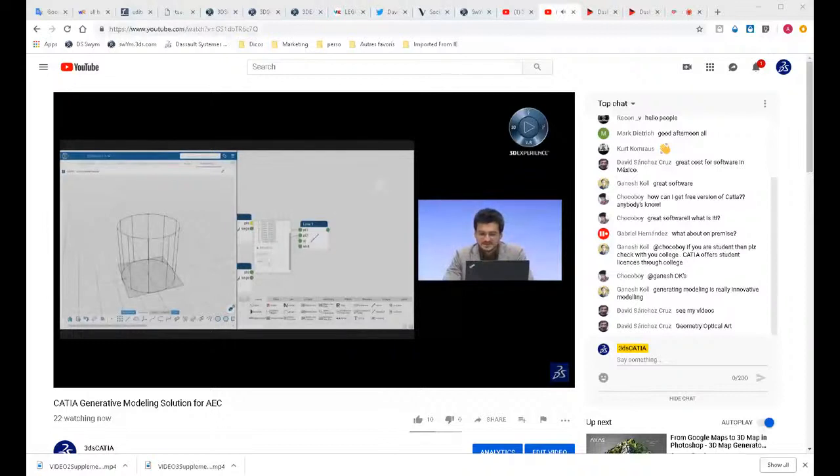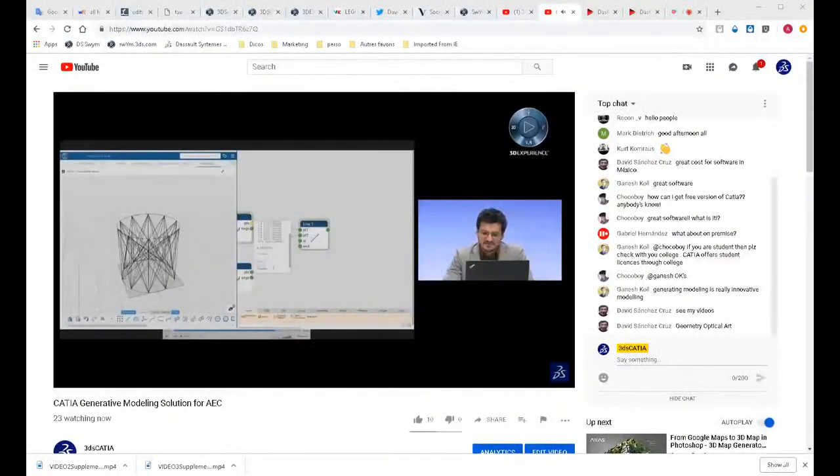Here I can actually embed a sub-function into the function. So here I'm going to deepen. Deepen is a very important list management operator. There are many, but this one is very important. It increases your list by one dimension, meaning that here you can see that now I have 10 lists of one element each.